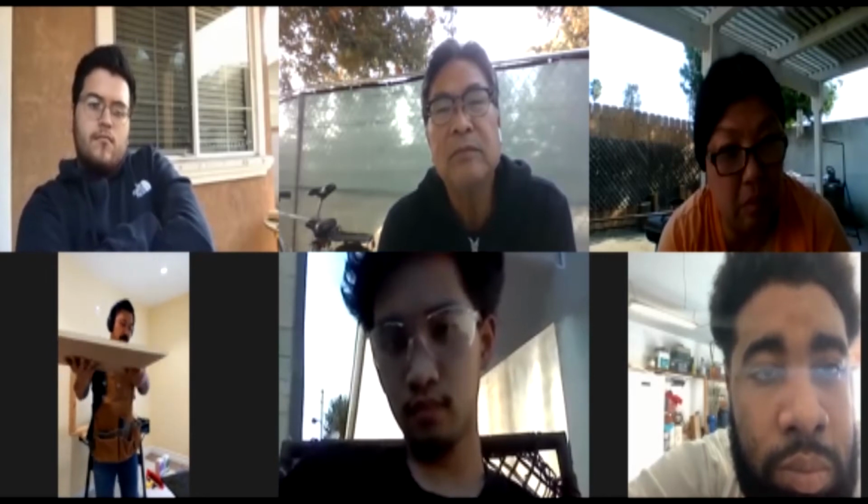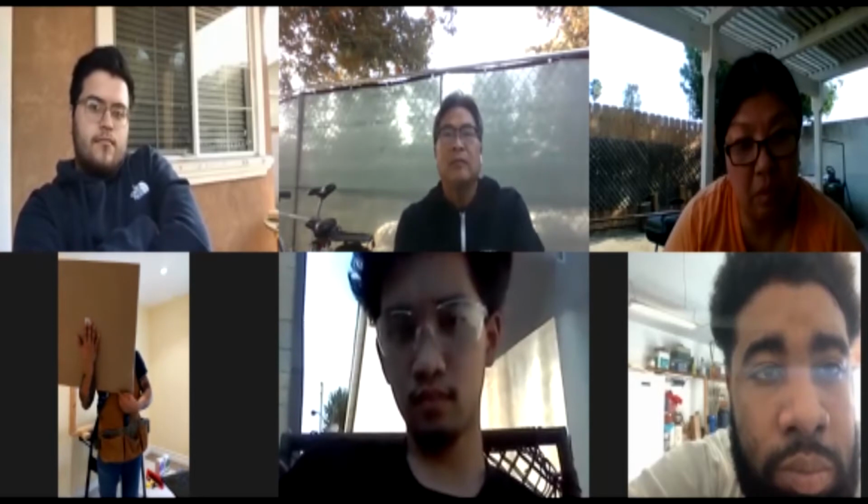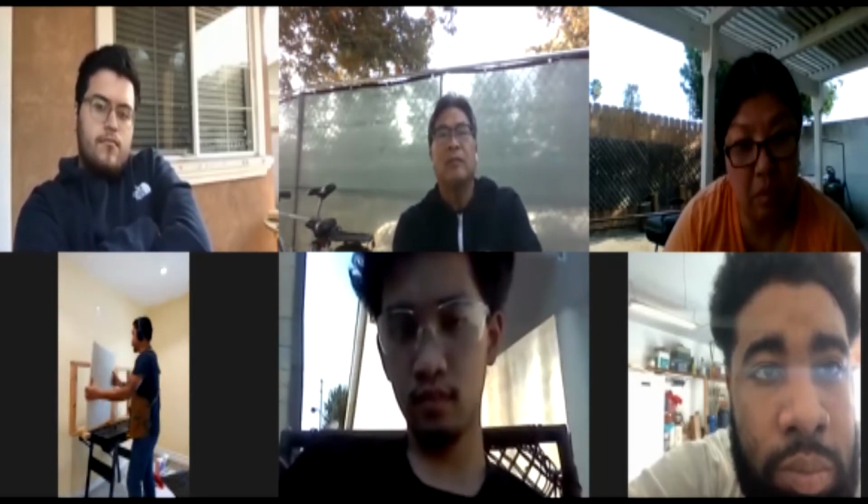The paper on top actually goes around it. And if you look on this side, there's white, and also on this side is white. That's the non-factory side. So you always want to keep your factory side on the ends, because when you join two factory ends, it's actually a better joint because it's 90 degrees, right? It's 90 degrees from here down to here. So you always want to keep your factory side.